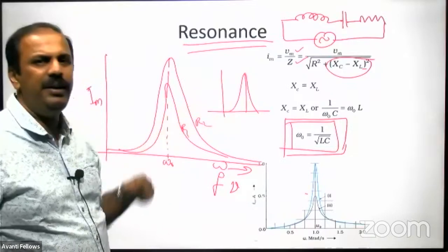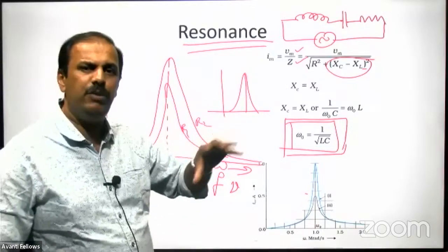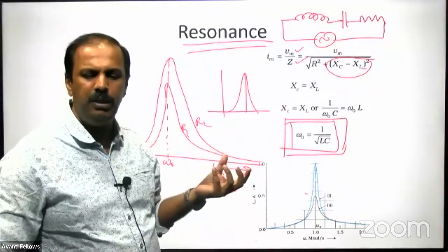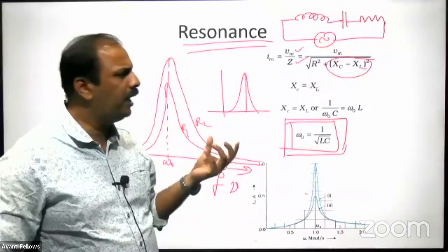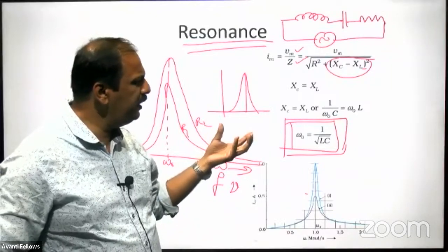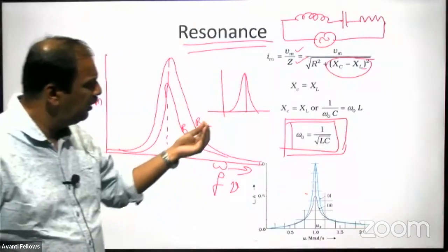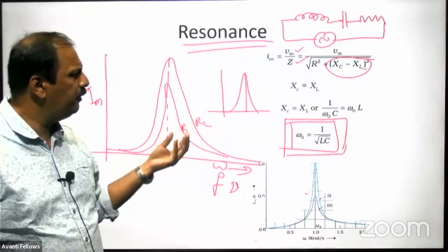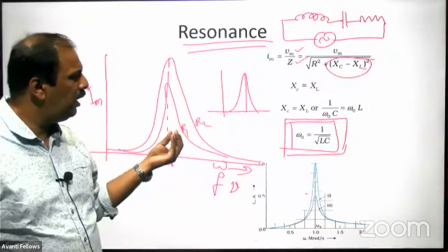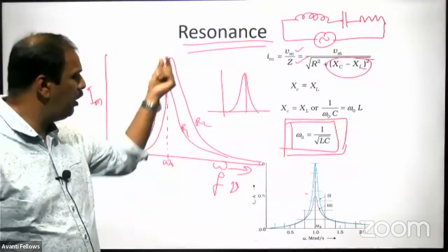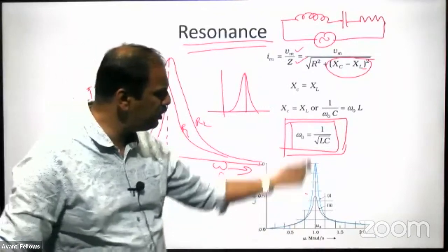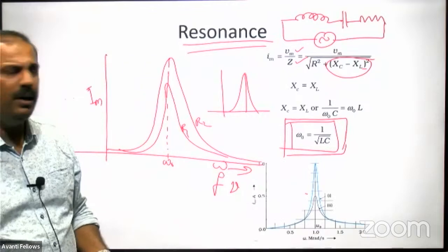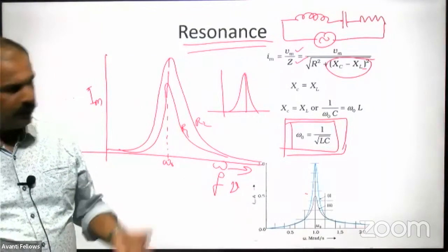And you see here we have an inductor also. When you are changing the band from one band to another, what we are doing is changing the inductor. When you change the inductor also, we will have a different value of resonance. So this resonance is used for selecting that value. Okay, this resonance is used for selecting the value of that one.